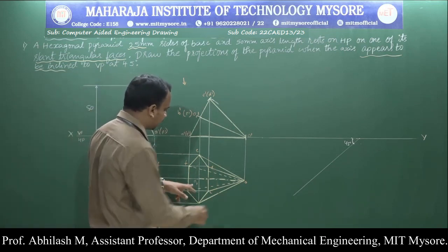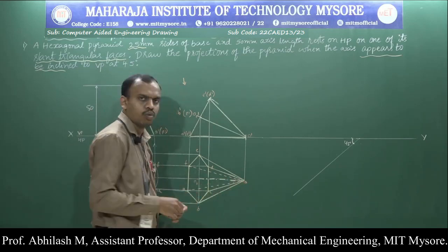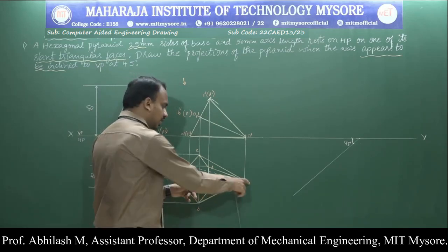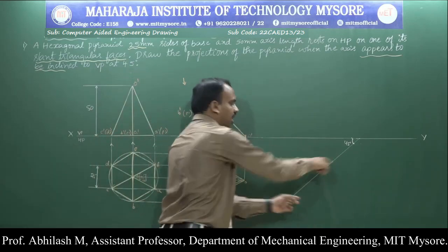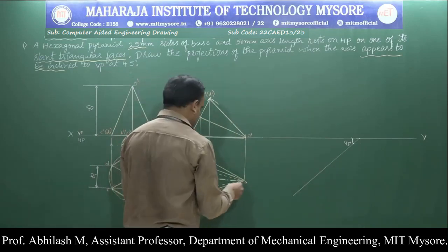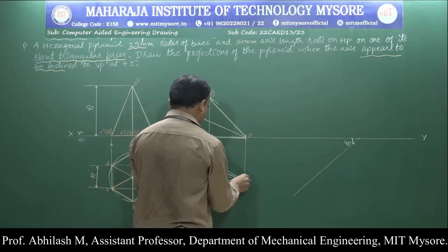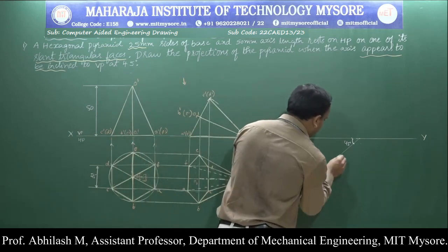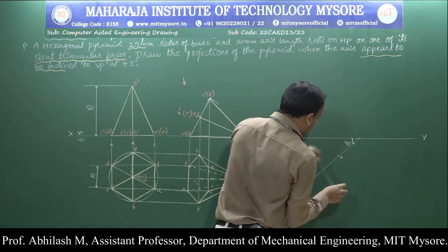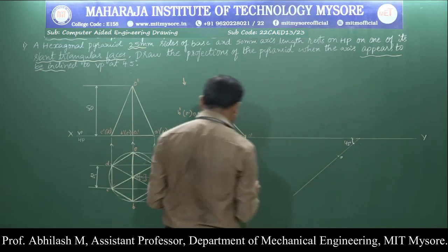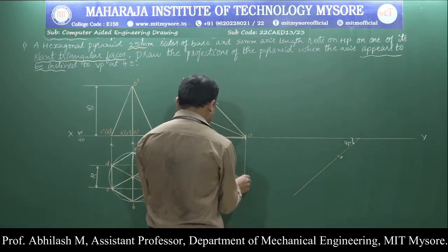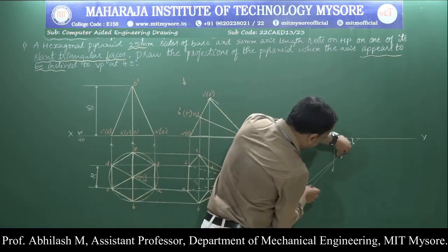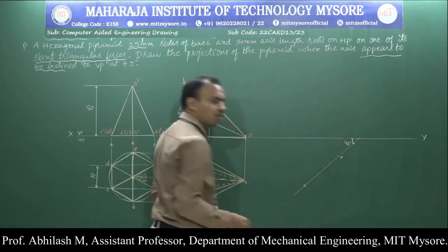There are two ways. First, you are supposed to identify O1 because they lie along the same line, and this is the one that has to be transferred completely. So measure the distance from O1, mark any point and call it O so that it becomes a reference for us, and draw a line up to O1.